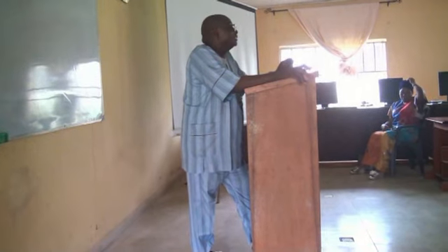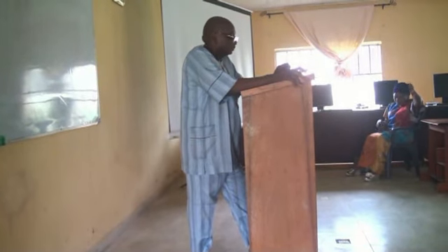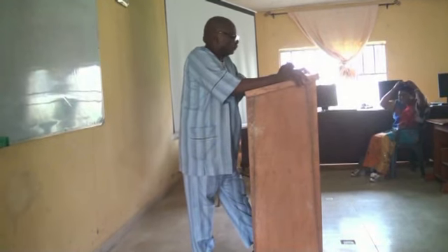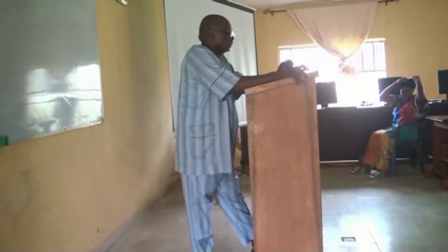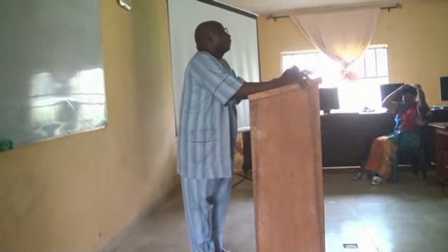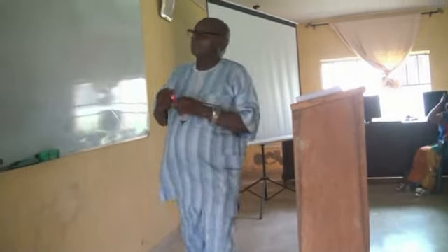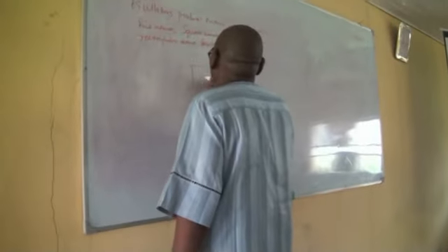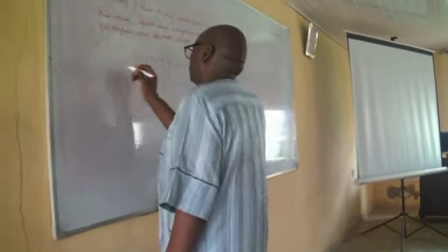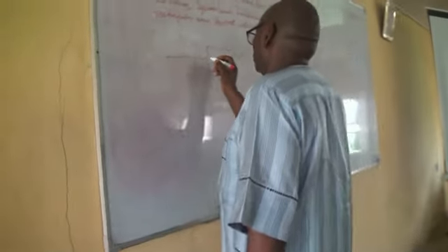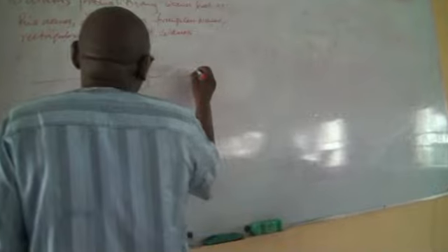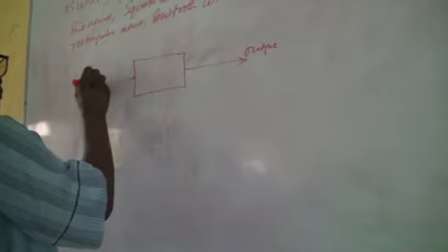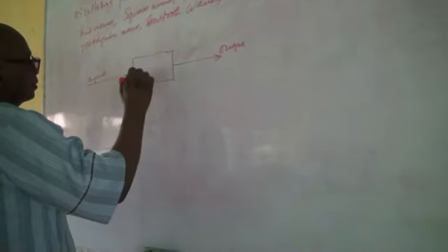Their operation is based on the principles of positive feedback, where a portion of the output is fed back to the input in a way that causes it to reinforce itself and thus sustains a continuous output signal. What I'm talking about is this feedback. Let's consider this to be a black box, okay? This is your output, right? This is your input. And this is an oscillator, right?